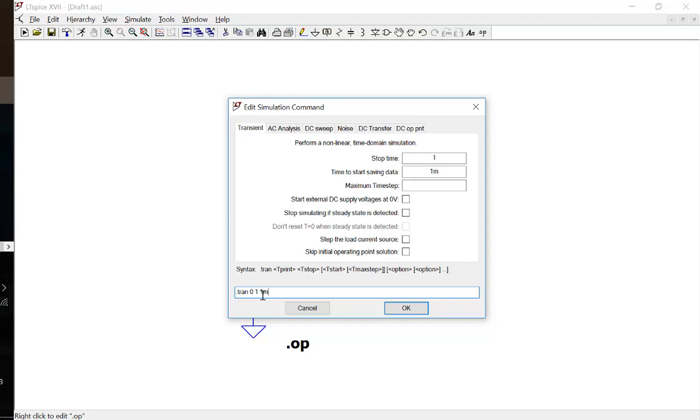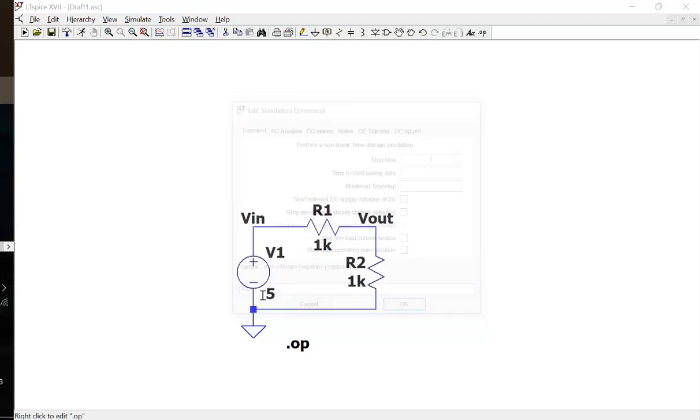And that's a formal way to do it, but usually I never did that. A lot of times I just put a transient analysis at 1. So it's going to stop at 1 second. It's going to start plotting from 0 seconds and will stop at 1 second. You know what I mean? But you should understand that if you see like 0 to 1 and the resolution is like 0.1 millisecond, you know what that means. But I just don't do that, okay? Just make it easier and faster.